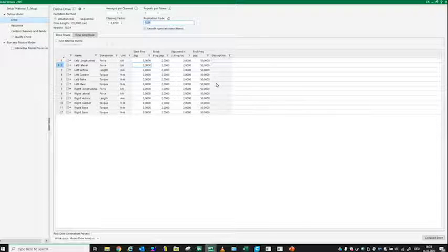So if I choose something else, let's say MTS test, this one will generate another white random noise, but exactly the same one if I always use the same replication code. So no matter on which computer you type in MTS_test, you will get the same white noise and can compare it to each other. This is pretty cool too, when we add some channels, or I had something set up wrong and I want to recheck, I just added a channel or something and want to recheck if the parameters stayed the same and compare simul drive previous and simul drive current with each other. I can type in this replication code and then lay both over each other and compare them.